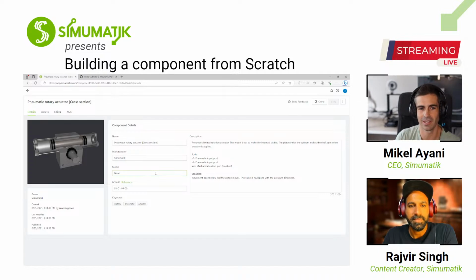So it has been refreshed somehow. We use these tabs to jump between 4 different sections. So we have the details of the component, name, manufacturer if we want to add the real manufacturer. If it's a component that we just created and came up with ourselves, we can just put our name. If it is a known model, there is the E-class, I think we mentioned it in another webinar, which is a quite international component categorization system. So you can click on the link and try to find an E-class.